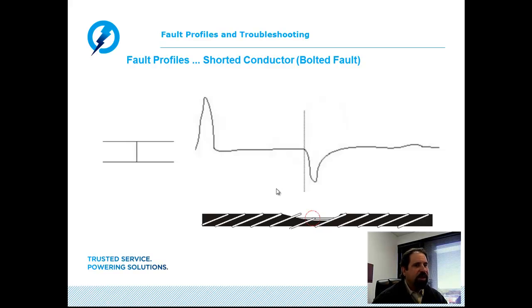Now, the radar is very complementary here, because if we were to try to find this fault using just the surge generator and we're not producing any sound, it could be very, very difficult to get a pinpoint on this fault. The time-domain reflectometry technique of pulse echo greatly helps us out here, because now we can physically see the fault, we can take a measurement to that event, and at least now we have a distance to approximately where this fault has taken place. We still need to work out some type of pinpointing methodology.